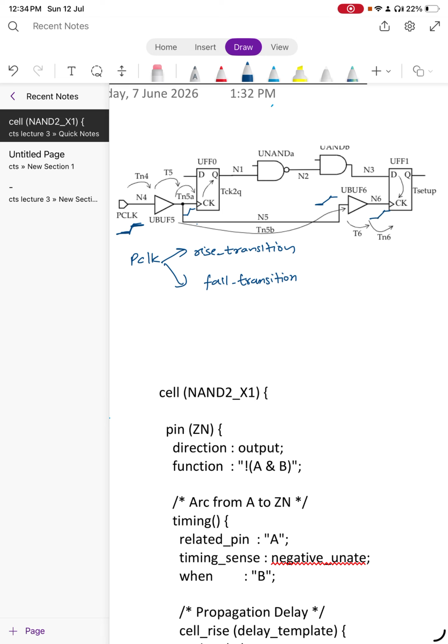and we have some rise transition over here. So for all these gates, we will only consider the rise delays because we don't have the possibility of using fall delay in this case. Correct? Because in dot libs, we are having both rise delays and fall delays. So in this case, since we have the transition like this, we will have only rise delays calculated from the dot lib.